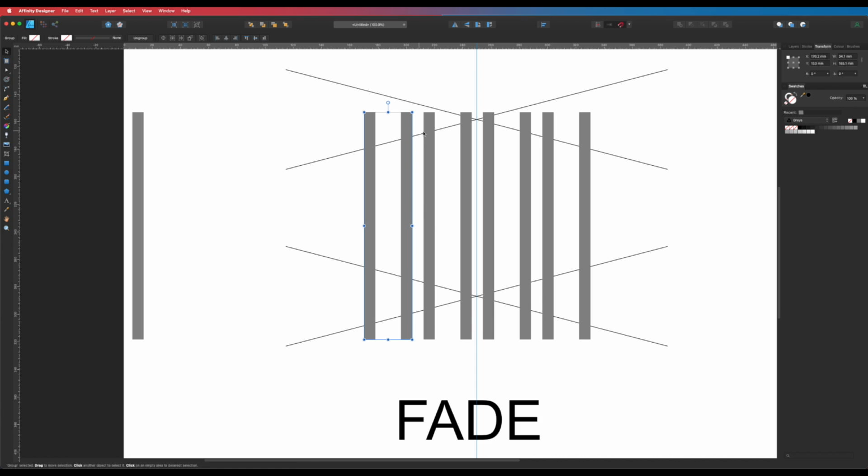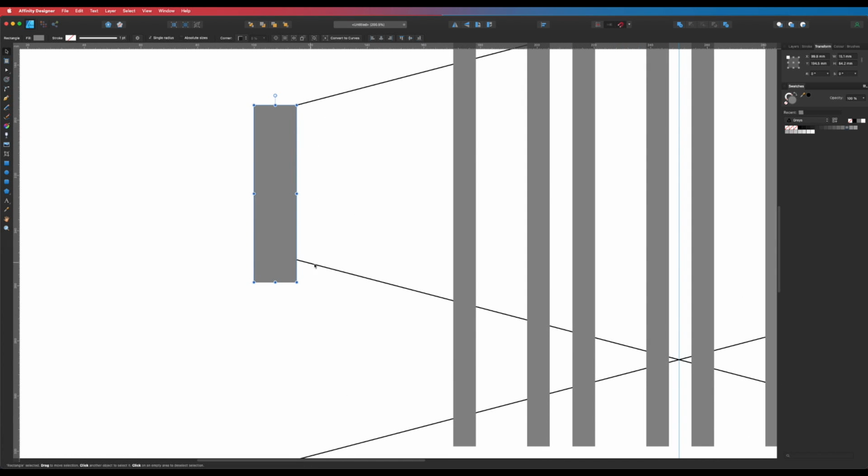So now, again, I need to create a center point for this. I'm not too sure what the distance is between these, so I'm going to press M and go to this. You can see how nicely it highlights that little edge there. Click and drag, and I'm going to drag all the way down to there. I'm just going to expand out so you can see, and this will be my halfway point here. If you wanted to see what the height of this is, 128.4, I can just divide that by 2, so I can go divide by 2 and hit enter, and that would be my center point right at this point here. Now it's obviously the inside. This is my center point here, not the outside bit, it's the inside bit.